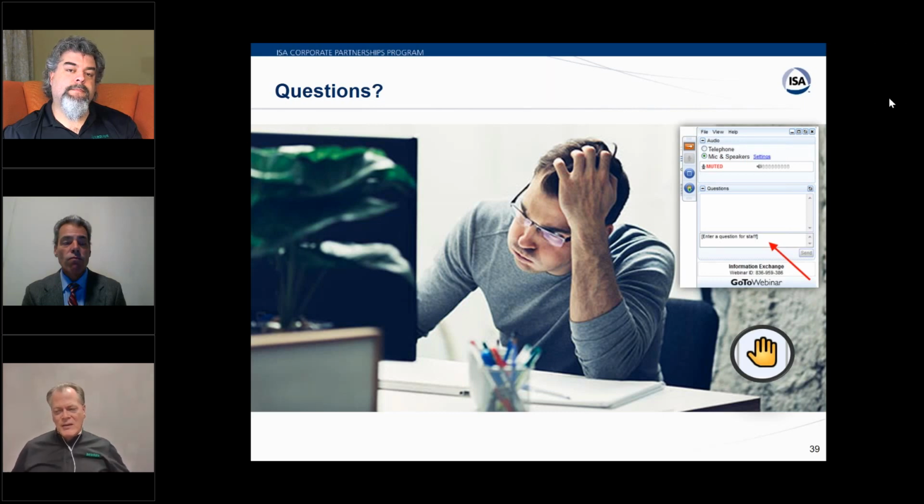Yeah, that's one thing I've learned with this session, is that you kind of have to back into these intervals. There's no magic formula out there, and so when you determine your SIL, that's going to be your lead determinant on an interval, and then you need to see if you're not doing it enough. You got to figure out ways to do it more often.